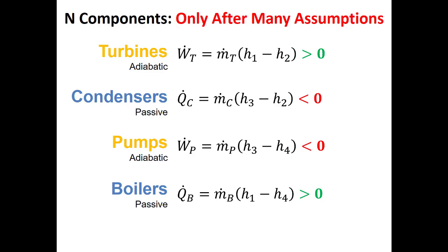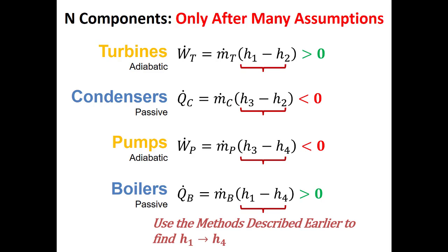So here are the equations. These are actually, because the state numbers are here, just the equations for the normal 4-component Rankine cycle. But functionally, the first law analysis is not different when you add more components, except that the state numbers might change. So if it's power, m dot times h in minus h out. If it's heat, m dot times h out minus h in. And let the sign convention tell you where it's positive and where it's negative. And you add stuff together.